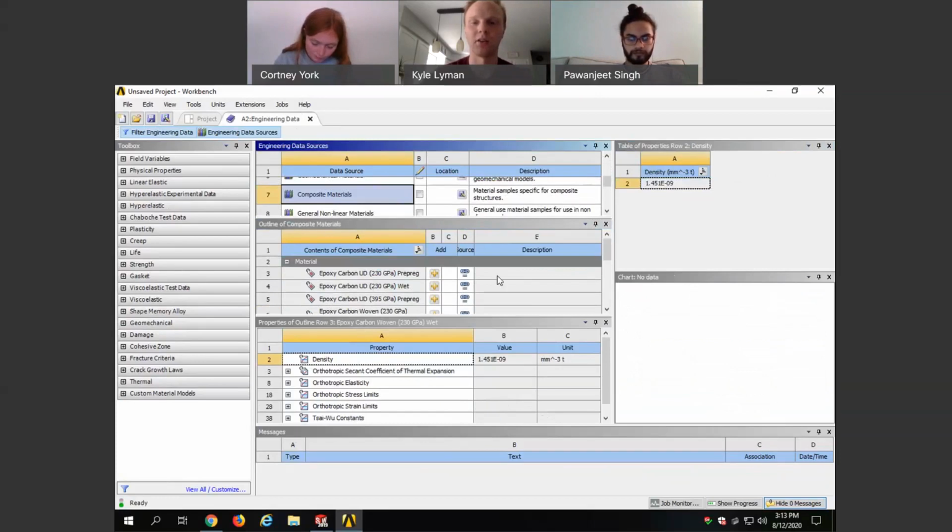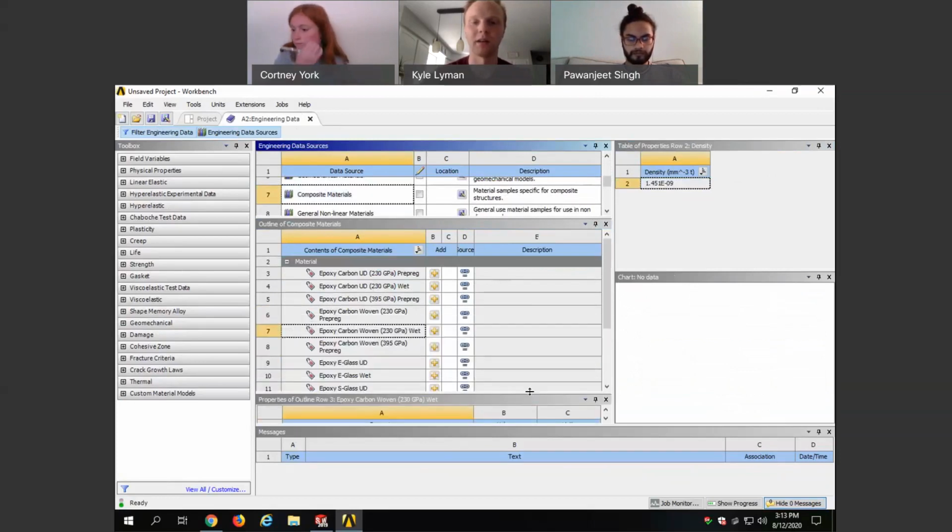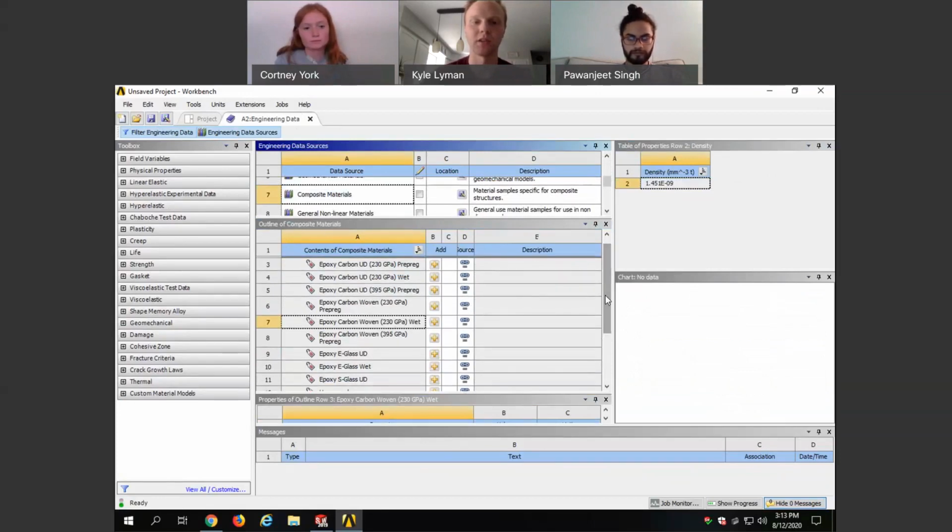So, just to give you a quick rundown on the material type abbreviations, epoxy carbon means carbon with an epoxy resin, and UD means unidirectional, and that means that all of the fibers are aligned in the same direction. It's not a woven pattern at all. Imagine if you laid out 1,000 pieces of string all in the same direction, and they're just held together by the resin. So it's really strong in one direction, but it breaks apart in the other direction. So we don't use unidirectional. That's a bit too specified.